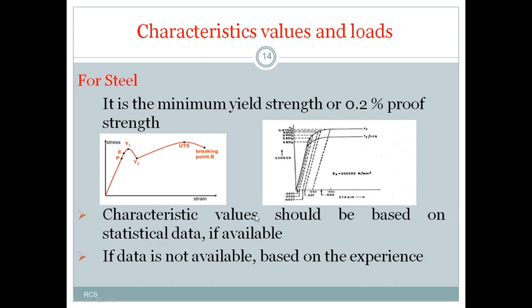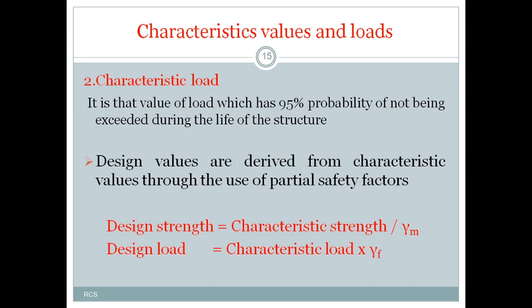The characteristic value should be based on statistical data if available. If data is not available, we can calculate the characteristic values based on experience. Then what is the characteristic load? The characteristic load is that value of the load which has a 95% probability of not being exceeded during the life of the structure.